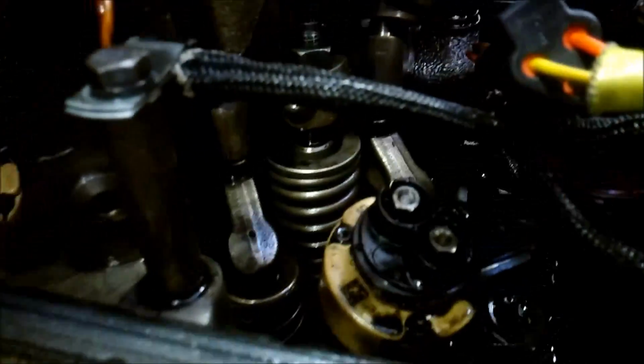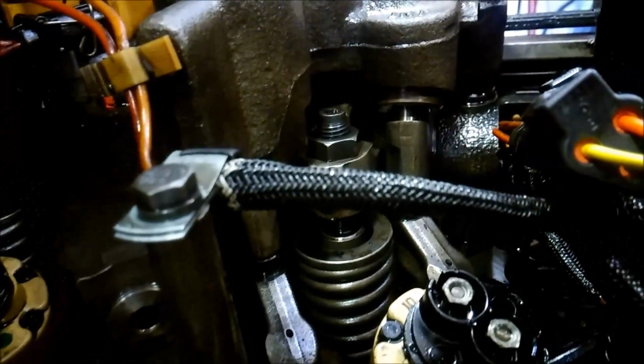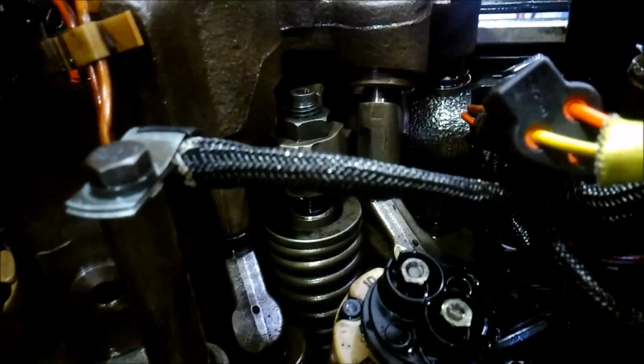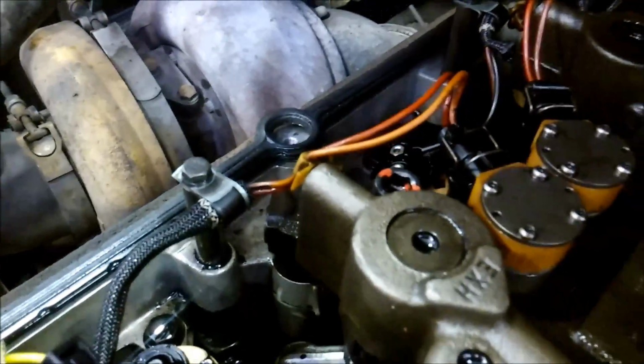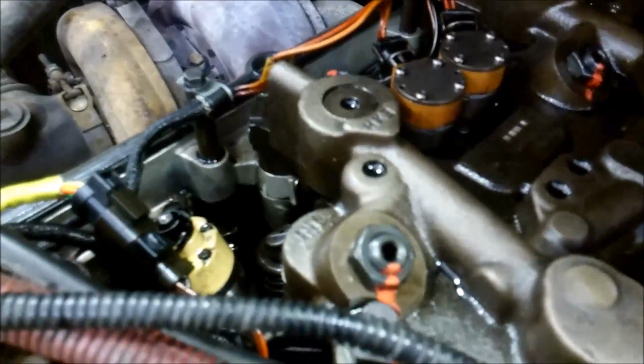Now, on the not responding or not responding properly codes for IVAs or Jakes, you need to look at your overhead adjustment. Like we're looking at the IVA adjuster here. If that's off, even though you might not have an electrical code, you might have a mechanical fault, and that could cause that code to become active.